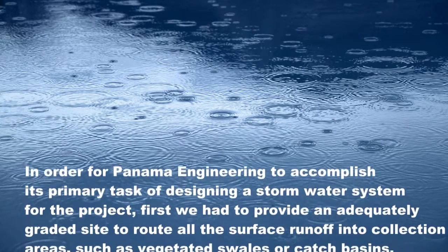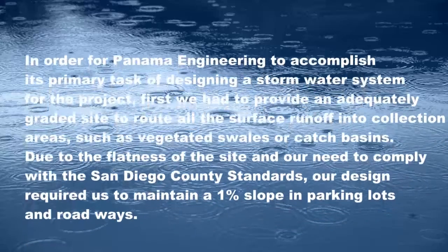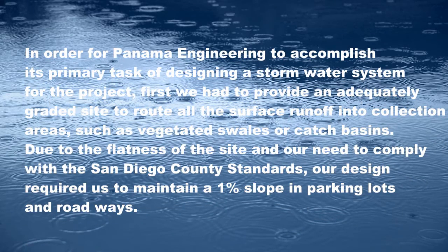In order for Panama Engineering to accomplish its primary task of designing a stormwater system for the project, first we had to provide an adequately graded site to route all the surface runoff into collection areas, such as vegetated swales or catch basins. Due to the flatness of the site and our need to comply with the San Diego County standards, our design required us to maintain a 1% slope in parking lots and roadways.